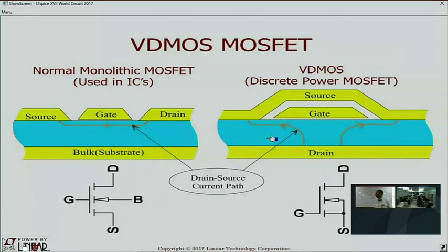Okay, now the source is one massive metallization, just covers the whole side of the whole thing. Now you could put the drain on the same side of the die as the gate and the source. That is a normal thing to do. That's actually easier to do.